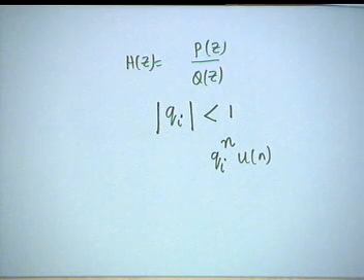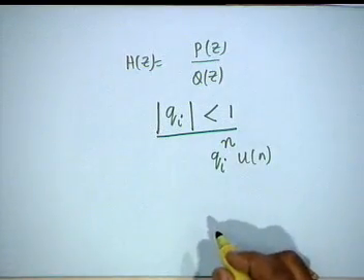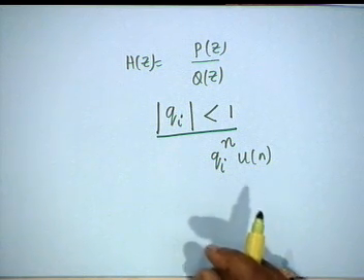So, it becomes an unstable system. Not that unstable systems are not useful, okay. Unstable systems we require for oscillation. If you want to make a digital oscillator, then we do require an unstable system, but not for any other purposes. So, the poles q i must be inside the unit circle. It is a repetition of what we had stated earlier.